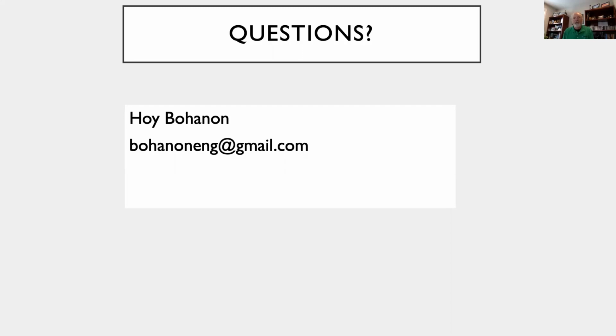Well, I'd have to go back and look at the numbers because I think of it in CFM per person. So I'm sure somebody on the task force has gone through all those numbers. You've got a high density of students in the school. You've got a requirement for ballpark 15 CFM per person. So there's a lot of CFM you're going to have to run through that classroom.